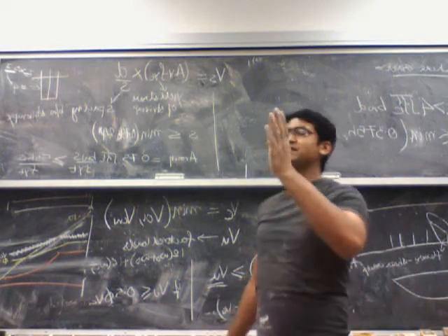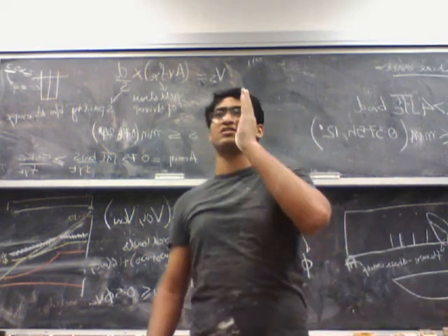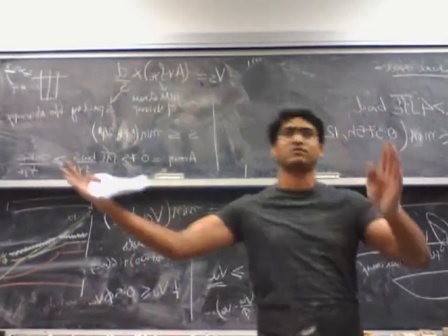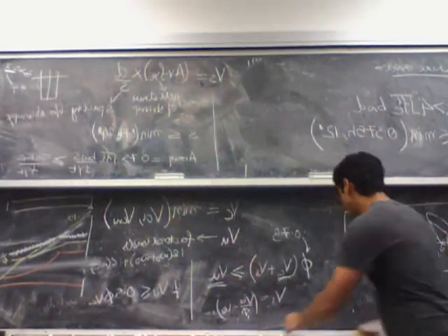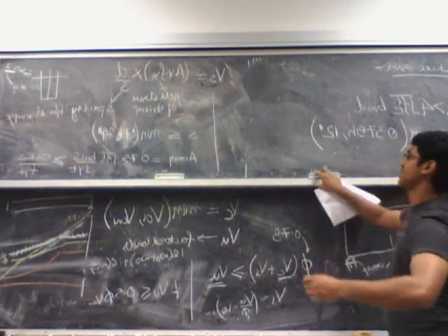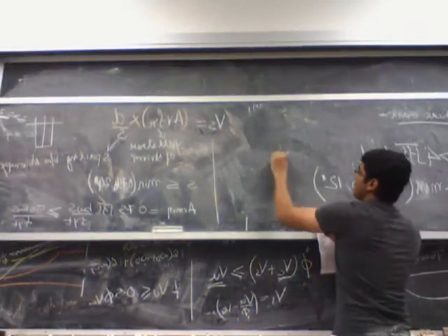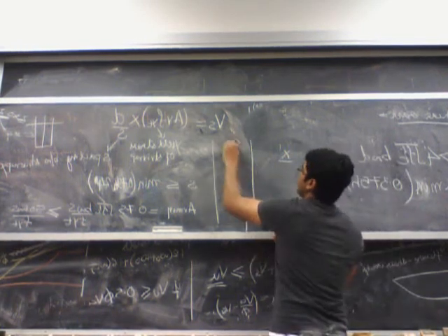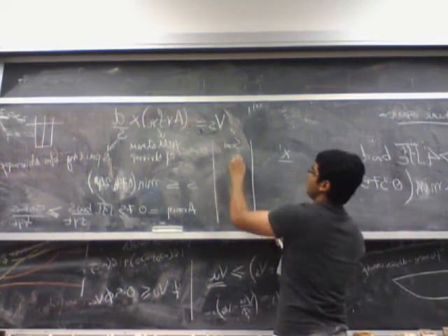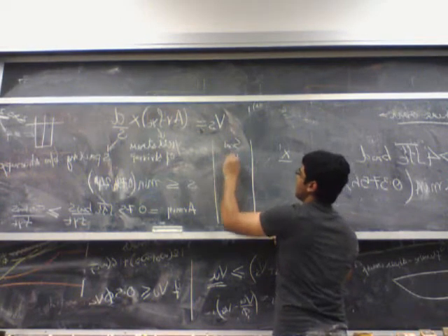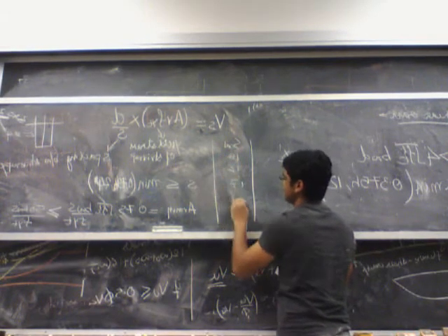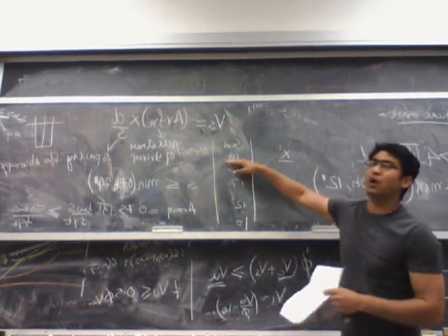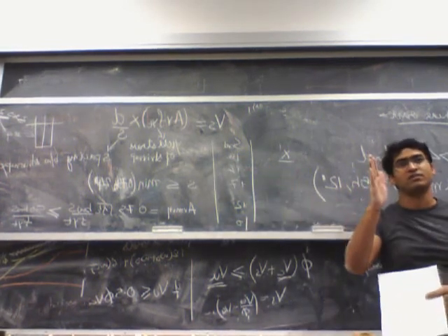So the spacing that you provide at a particular cross section is not just valid for that particular cross section. It's valid for a few inches on both sides. So let's say if you look at the solution for the assignment, what I had was the value of x, that's the distance from the support. Then I have s calculated, and s calculated was like 18 inches, 16 inches, 17 inches, 12 inches, 10 inches. So these are the required values based on that particular cross section.